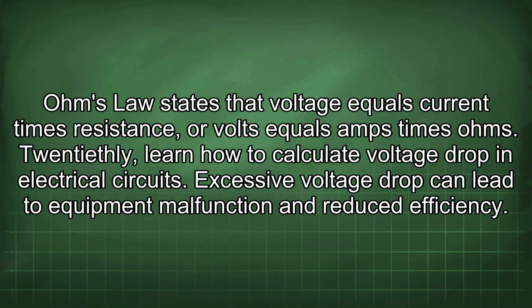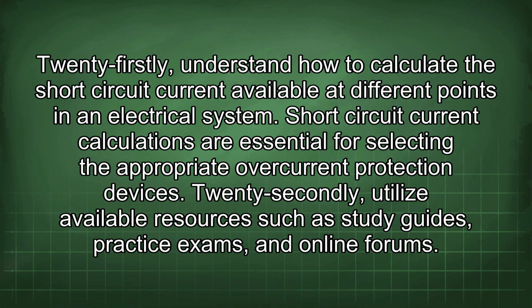20thly, learn how to calculate voltage drop in electrical circuits. Excessive voltage drop can lead to equipment malfunction and reduced efficiency. 21stly, understand how to calculate the short circuit current available at different points in an electrical system. Short-circuit current calculations are essential for selecting the appropriate overcurrent protection devices.